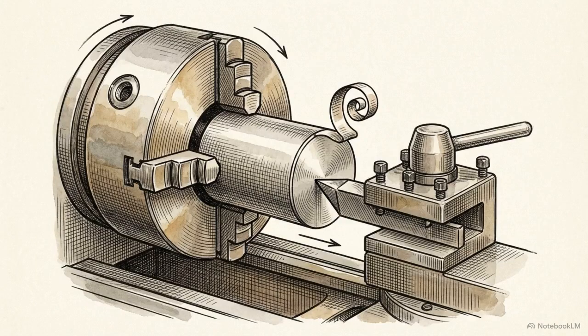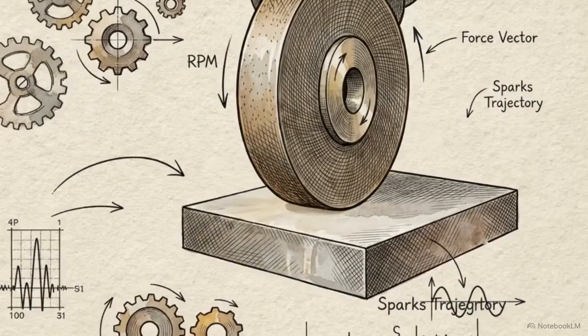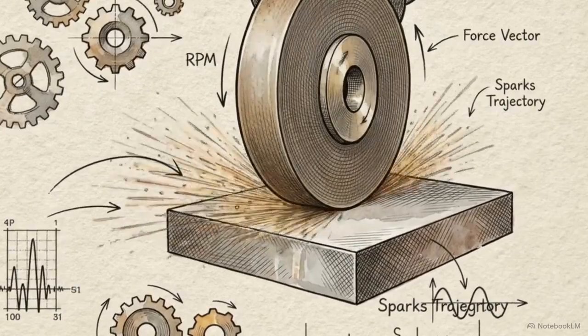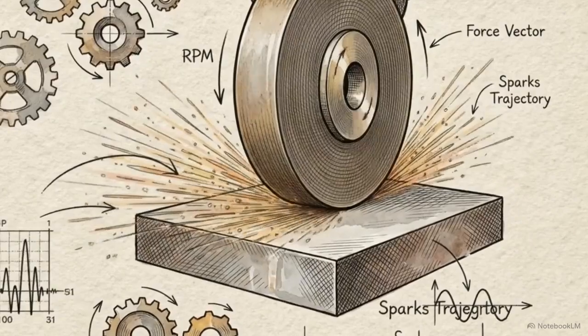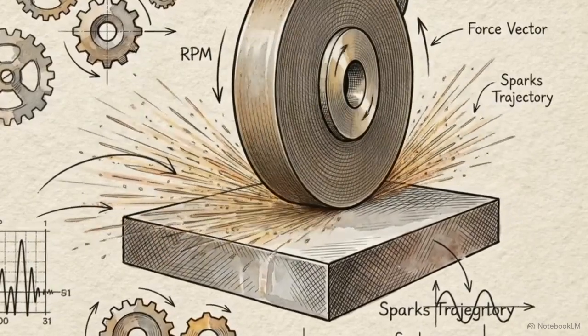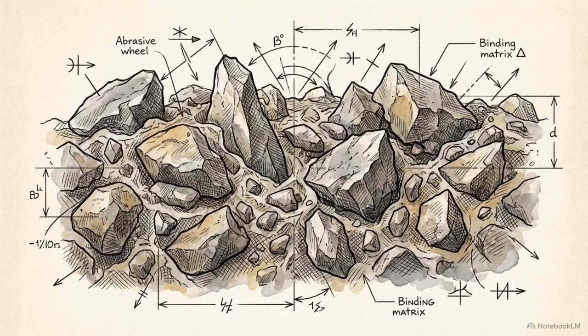Moderate, smooth finishes are achieved through turning on a lathe or milling. These cut the metal directly and leave clear, geometric lay patterns on the surface. Extreme environments, like aerospace bearings and high-stress engine internals, require the super finishing tier. To drop the RA value drastically, engineers switch to grinding. This abandons single-point cutting blades entirely, using high-speed abrasive wheels to shear away microscopic amounts of material.